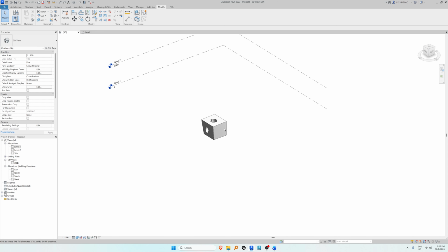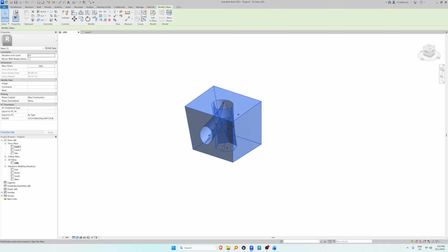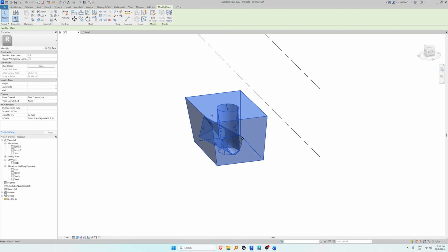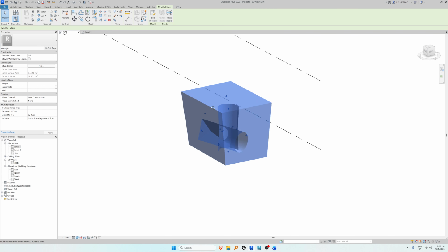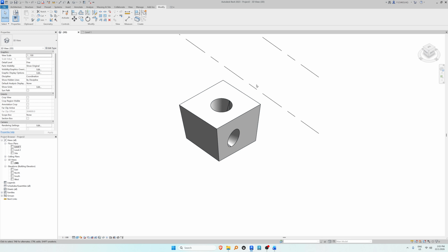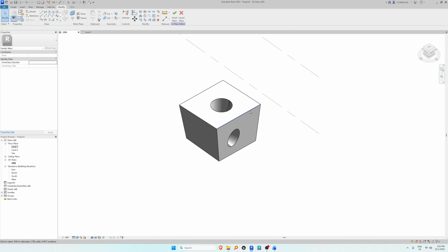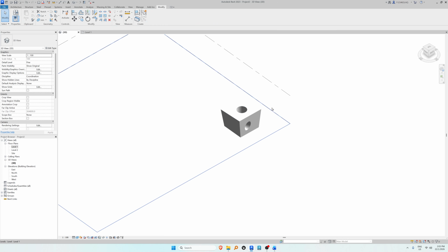We finish mask. So now we have exited the mask mode. As you can see, it changed back to the old Revit interface, the main interface, and we don't have these controls for the masking anymore. But we can still edit some of the things because we have all these arrows and stuff. So just undo this just to show you what we can do. But you cannot edit the actual masking. To do that, you have to select the masking object, click Edit in Place, and then you have your old masking controls back. So you have to enter the masking mode to do that. I'm just gonna cancel mask for now. I'm gonna make a new mask.